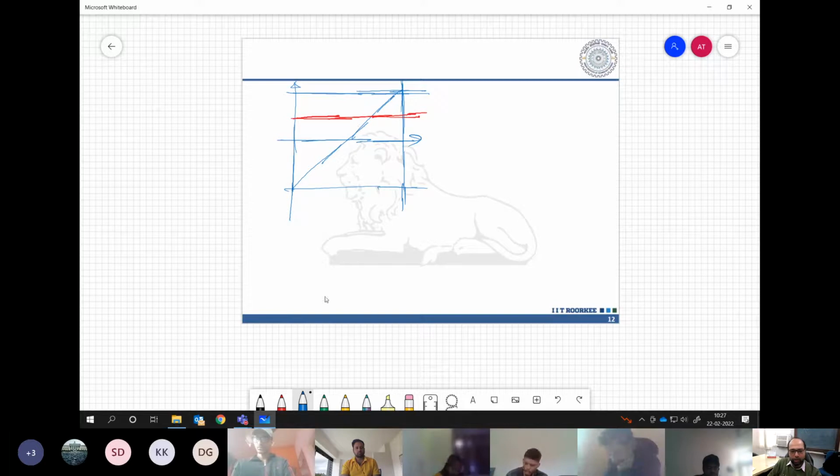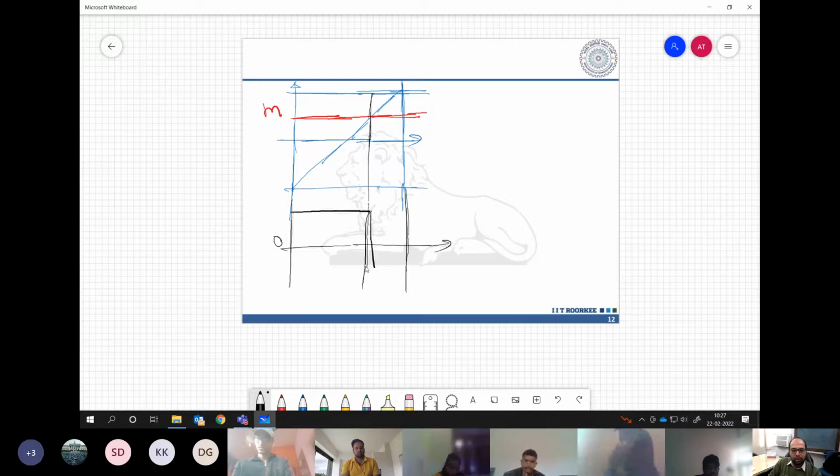Now in response to this modulating signal, what happens? We generate our gating signals, or you can say the pole voltage output. So how will the pole voltage output look? It will be a pulse, say this is the 0 axis, of this much width on the positive side and a small width on the negative side.